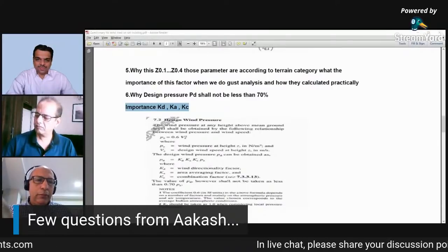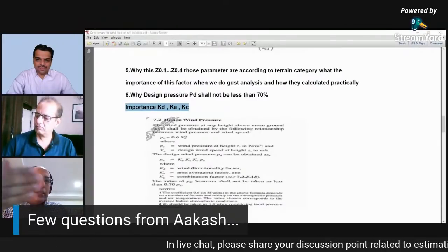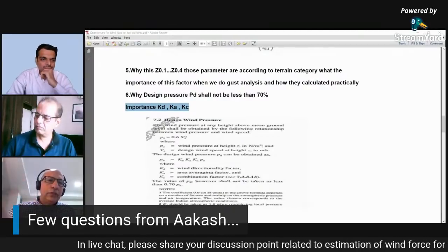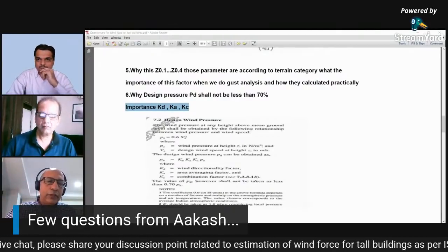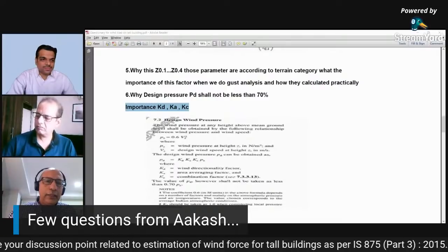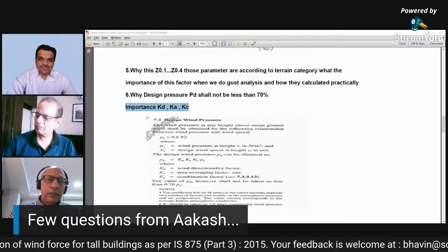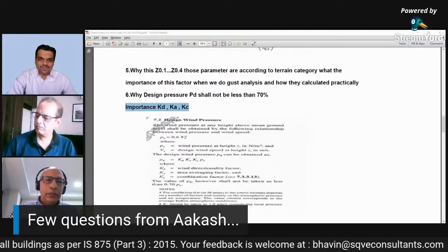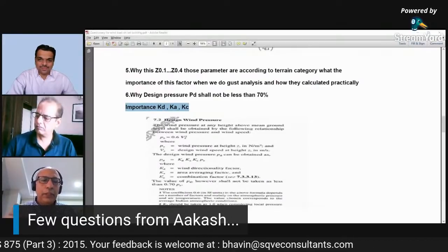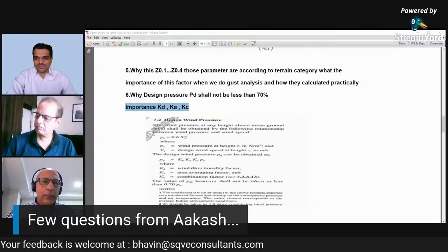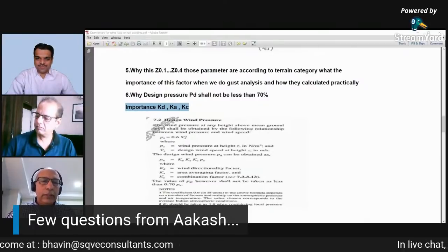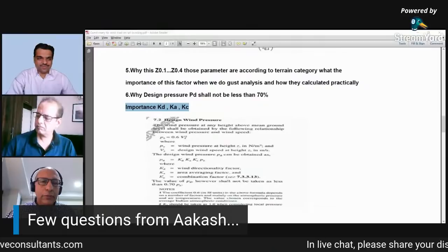It's going to be affected by a larger scale vortex that goes over a big section of that tributary area. Because of the size of that vortex, it doesn't tend to result in as high a peak pressure as the smaller scale vortices that occur at the leading edge, for example.